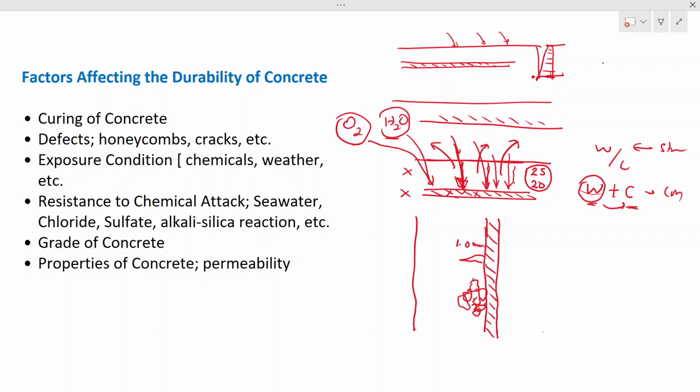Here there's a considerable honeycomb, so your reinforcement bar will be like this. The cracks have penetrated to the reinforcement, and the honeycomb is also in the zone of the reinforcement. The contractor doesn't seal the cracks or repair the honeycomb and just does the plastering.